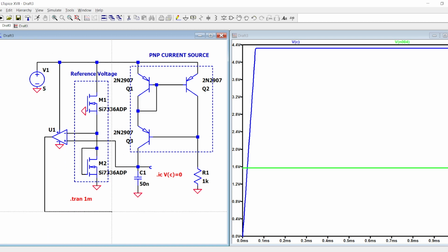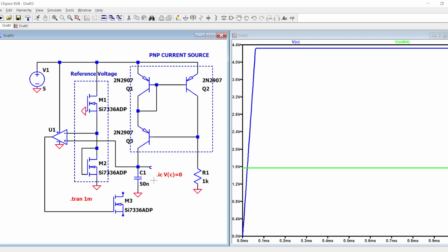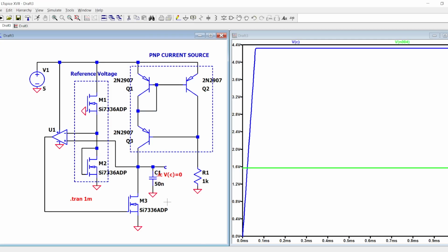like this. So this comparator will drive a MOSFET, and this will reset the voltage V of C. Like this. Now, I know that it is not exactly the circuit like this because the guy put 10 milliamps, 12 milliamps, which describes the slope of the turn-off phase.